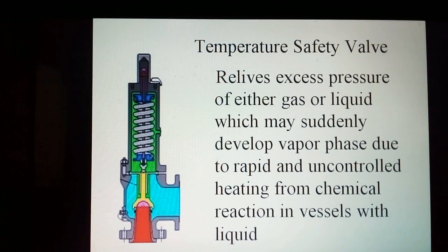The valve is usually a closing element in a heating system, but it is fitted with a thermostat. In the normal course of events, the valve will simply continue to be closed and maintain the integrity of the system. If something goes wrong and the system starts to overheat, the thermostat in the valve will react, and if the temperature rises high enough, will push the valve open and release the pressure that is always associated with excess heat. You will find pressure release valves on any hot water tanks associated with boilers.